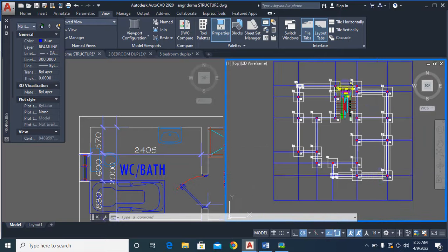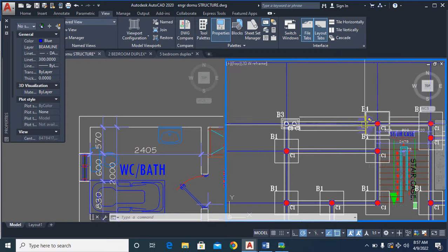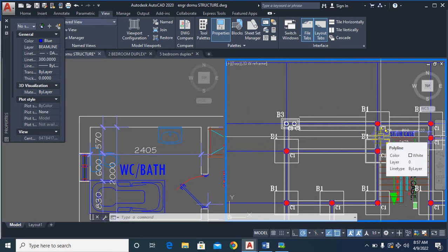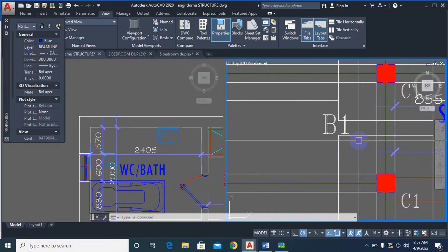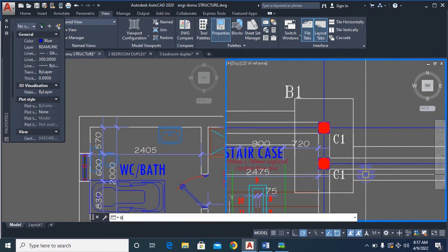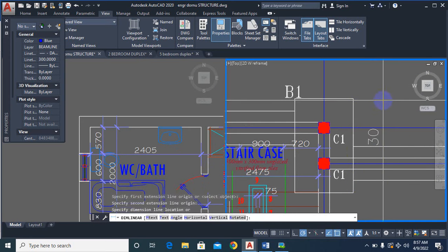By the time we run our design, if you can remember, I did not run this design by placing these base sizes. I just assumed a 1200 size of base. So I'm going to run my design assuming a 1200 size of base. When it fails, then I will have to increase. Sometimes it may give me a lesser value.